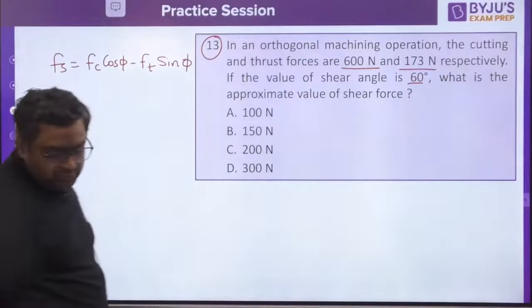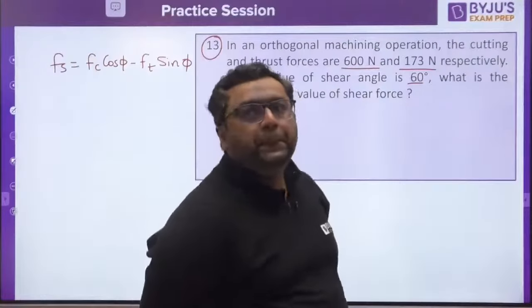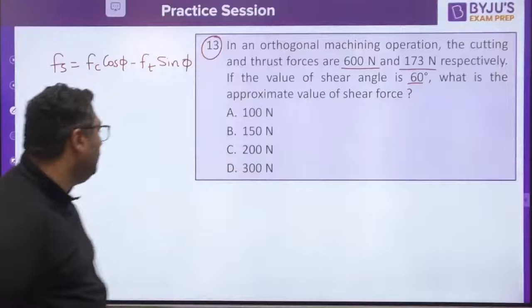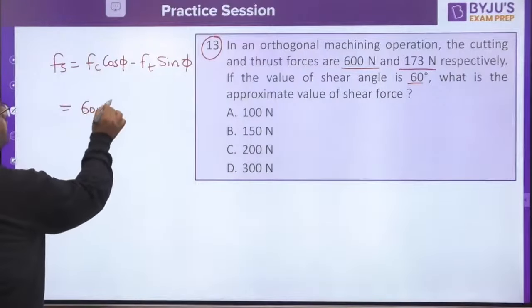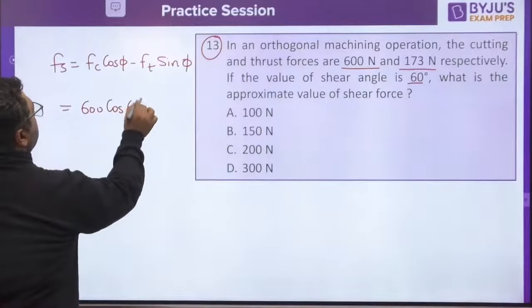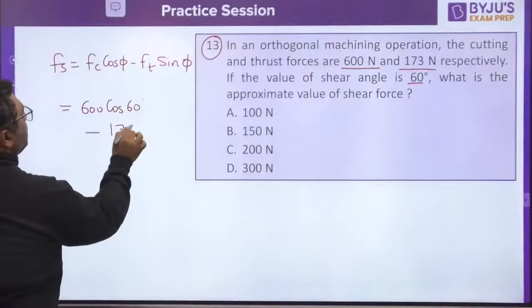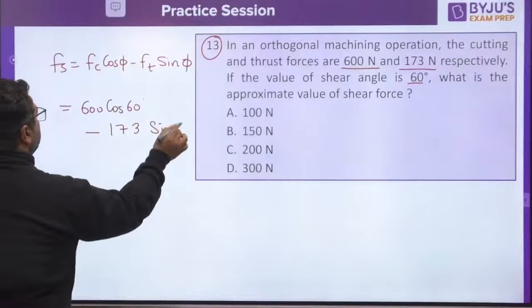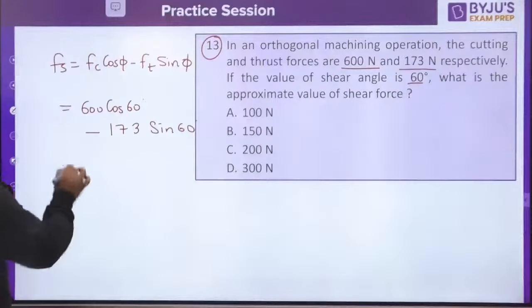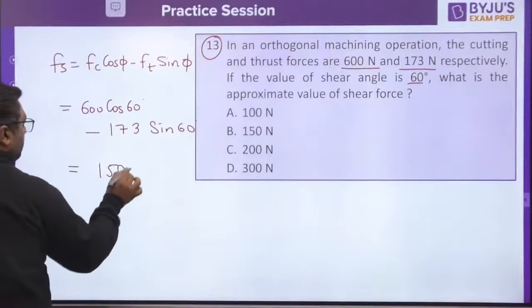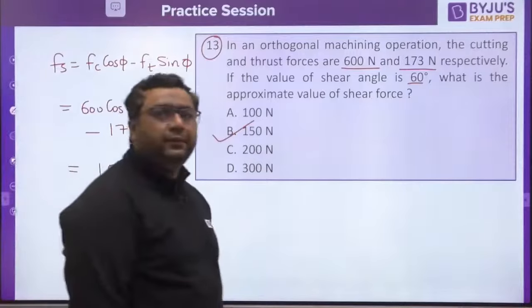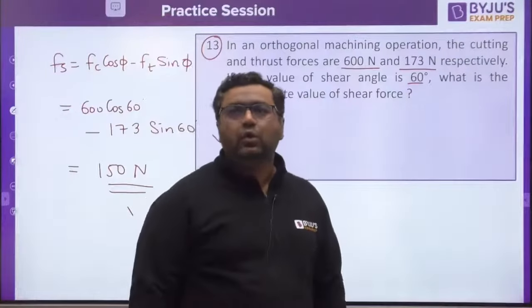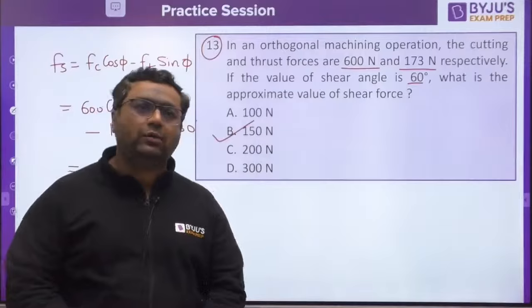Very good, very good. Rohan, wonderful. So cutting force is 600 cos 60 minus 173 sin 60. 150 Newton. Very good. Gaurav, Saikat, Omkar, Rohan, very good.